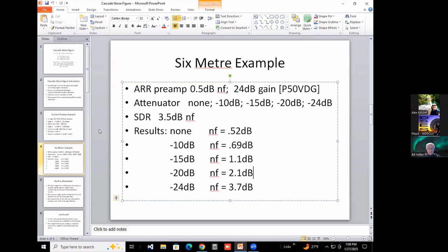Yeah, okay. The noise level on the speaker, on the output of the receiver, goes up, but the actual sensitivity, the front end noise figure, is what you're worried about. That's this guy up here that follows the preamp. If you've got enough gain after it, just don't destroy the gain. But even a 10 dB pad doesn't ruin it very much. Like I say, on 6 meters, it doesn't make a difference anyway, because there's so much noise on the band when you get down to these kinds of noise figures.